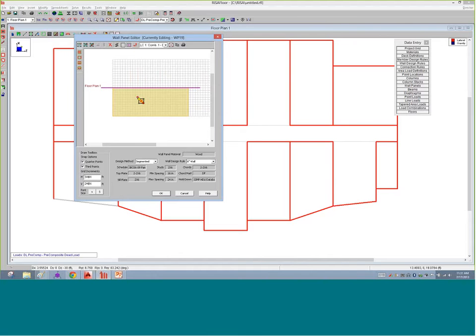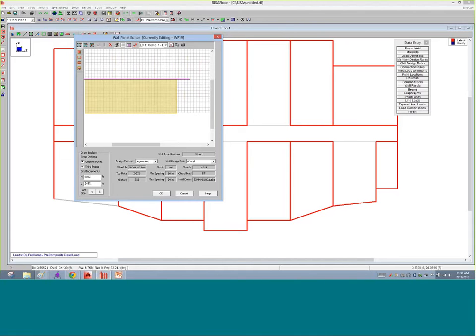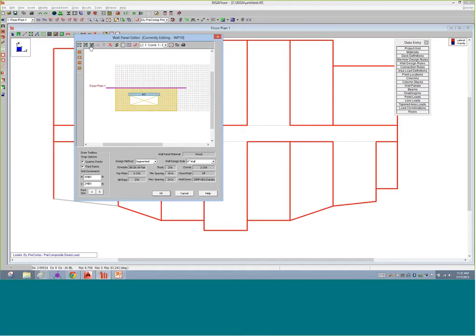So I'm going to draw just a couple of openings representing what's happening in this model, and you'll see here, actually, I got a little big here. I'm going to do it one more time and just draw an opening in. Once you draw that opening in, you'll notice a header pops right onto the top of that opening, and I can create regions just around that. Now, if I didn't push that region button, not to worry, it would have done it for me once I pushed solution. It would have drawn these regions in. And these regions, what we call these drawing regions here, are just like I mentioned, those segments.